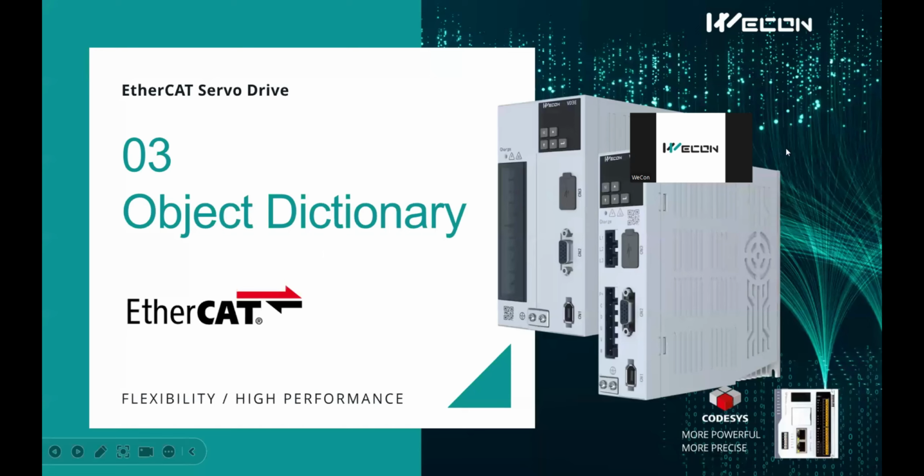And here in part 3, I will introduce the object dictionary of our VD3E, and how to connect the limit sensor signal with the home of the servo. We connect the limit switch signal to DI of our driver. It is connected to the driver, not connected to the controller, not connected to the PLC. And I will also have another class to introduce our homing modes in the next weeks.